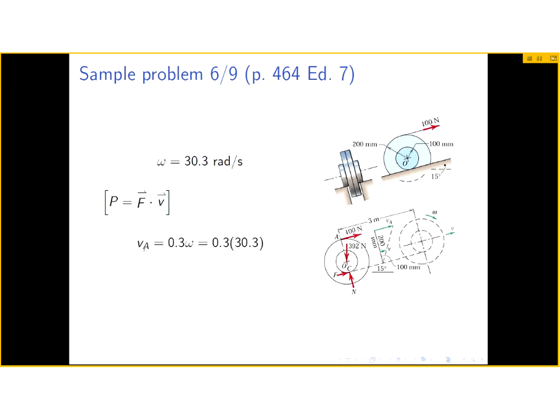But we still need to calculate that velocity of the cable, which is the velocity of A. And now we can very easily calculate this in terms of omega, because that's really what's explained by this velocity diagram. But it also boils down to applying relative velocity between the point A and the stationary point C. Remember that the contact point C, where the wheel rolls on the ground, is a stationary point.